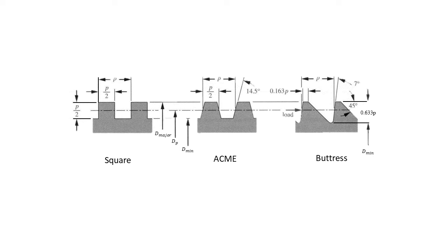In power screws, there are 3 thread configurations: square, acme, and buttress. Yes, acme threads do look similar to the trapezoidal thread shape found in ISO and UNS systems that we discussed earlier. They're also the most commonly used threads in power screws. They have easier manufacturability compared to square threads because they don't require perpendicularity. They work best for loads in both directions, whereas the buttress threads work well for load in one direction only. However, square shapes are the most efficient and strongest because they don't have any radial load between screws and nuts, unlike the acme threads.